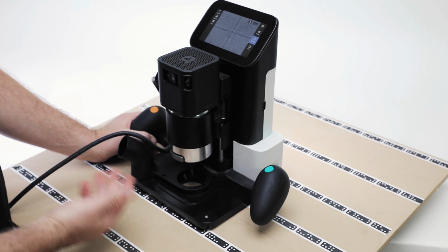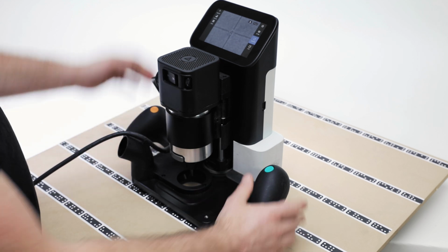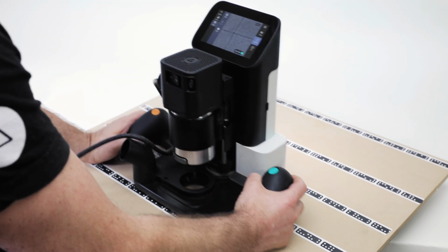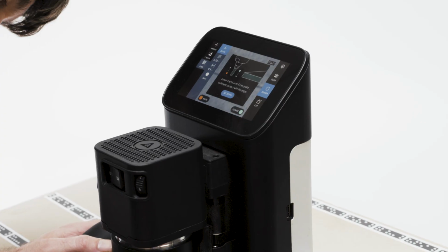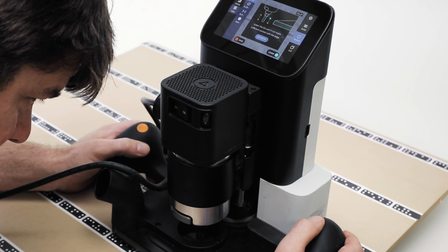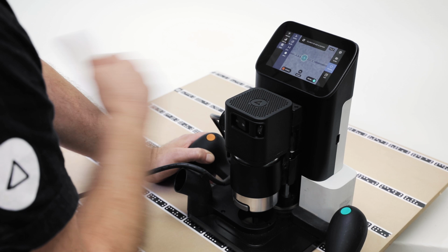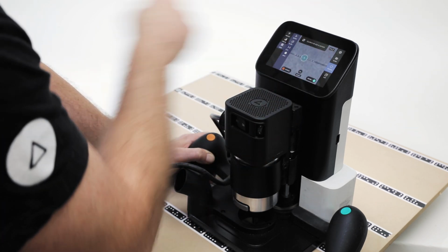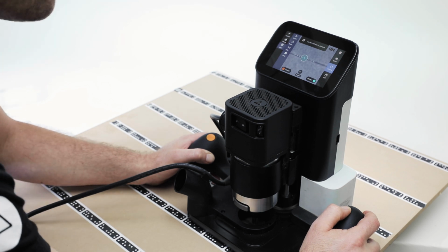I'm going to quickly find, on the screen I can see obviously my pencil mark. But to get it more accurate than what we see on the screen, instead of touching probe against the edge, we're going to lower it down and observe it, hovering right above that pencil mark. So I've lowered it. Once I'm happy with the height, I hit accept, and then I choose the center option. So I'm not probing the top of the engraver, using the point, which is the center of the cutter.